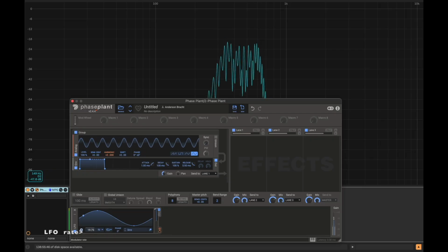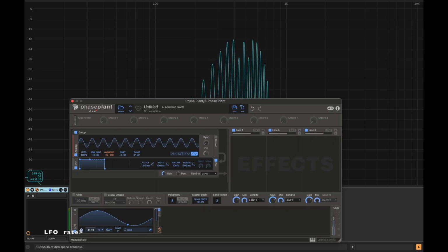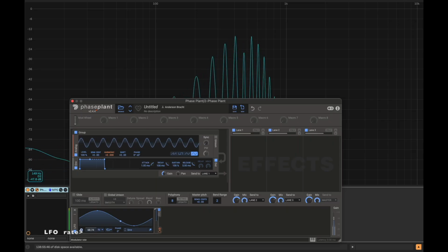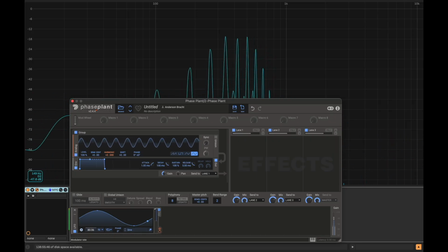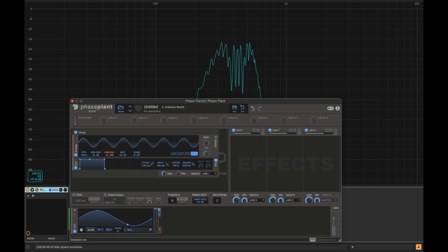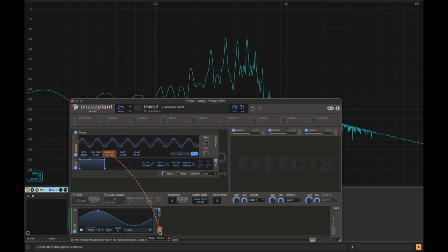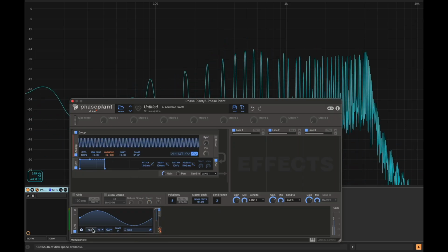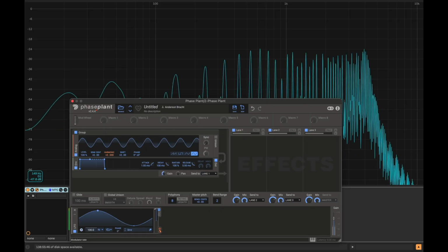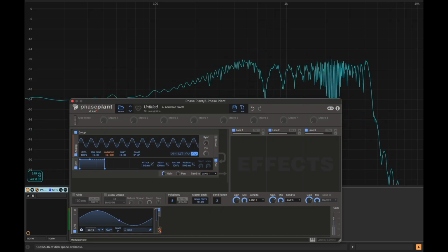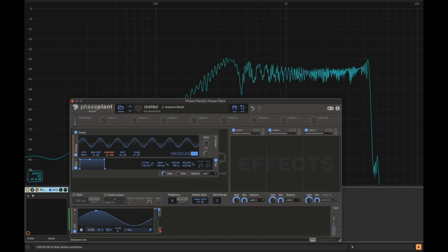When modulating frequency, once the modulator's frequency goes above 20 Hz, we can no longer hear the modulated change in frequency happening in real time. What we hear is newly generated frequencies in the sound. With the LFO below 20 Hz, we can track the frequency change with our ears. But once the LFO crosses 20 Hz into audible frequencies, we can no longer track the frequency changes because they are happening at too fast of a rate. Instead, what we hear is a more complex tone with added frequencies. This is how FM synthesis works.